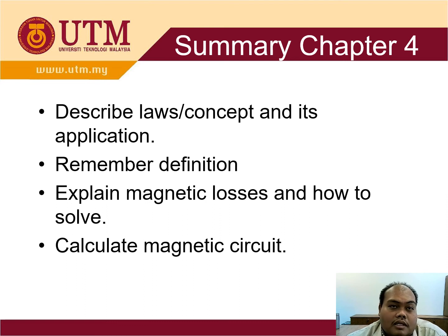And also, if the question asks you to have an air gap, make sure that you know the air gap mu r is equal to 1. So you have to recalculate again. Make sure you know that. And then make sure you know how to calculate B and H. Use the formula.